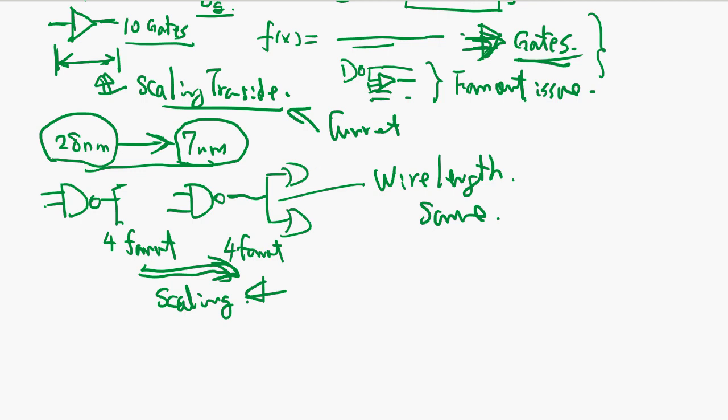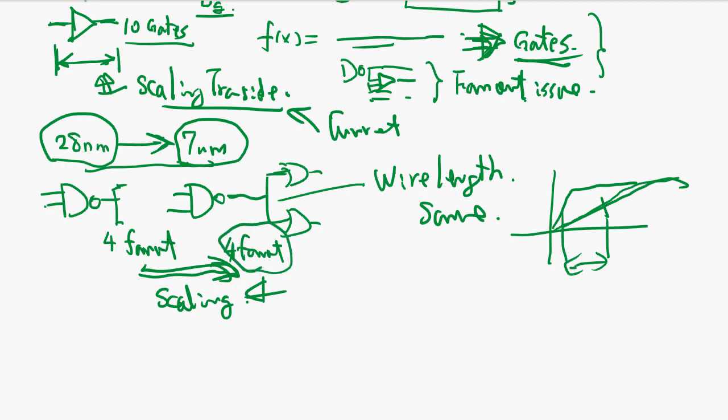And this is an exponential function, right? It switches like that or switches like that. This much delay is different, and you can't linearly just say, oh, everything scaled correctly, so it's still a fanout of 4. It's not. This requires a lot of chip testing for a new process.